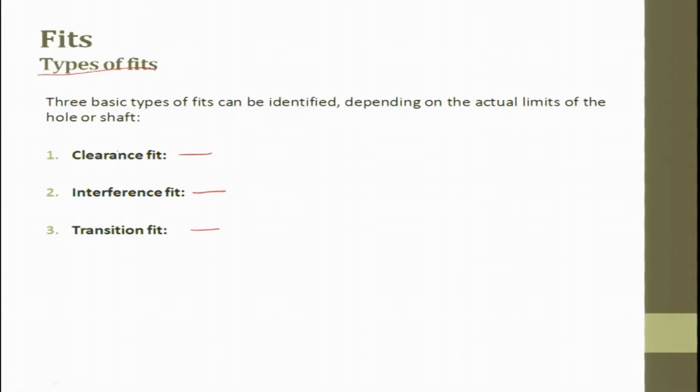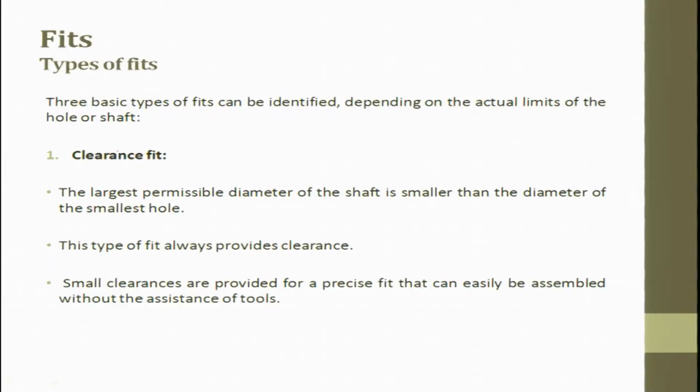So, fits are very important. These fits have a link to the previous condition, maximum material and minimum material, what we saw. And before that what we saw was tolerances. The tolerance, maximum material, minimum material, this leads to fit. Now, I think you will be able to appreciate why these fits are talked about more in manufacturing and also in metrology. So, what is a clearance fit?